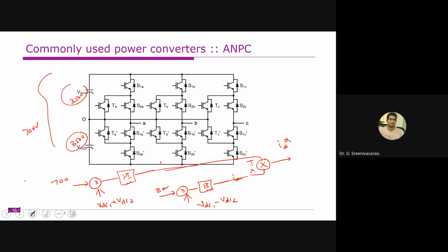Alright, like this. So you can use some auxiliary circuits, or you can use some advanced controls like model predictive control, or the space vector modulation technique with some small improvements, or else we can use multiple PI controllers to effectively balance the capacitor voltages. The rest of the things are the same. All this decoupled control remains the same only. Right. So now we will see the simulation.